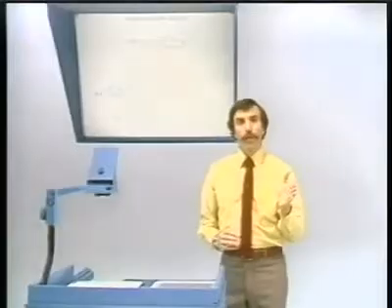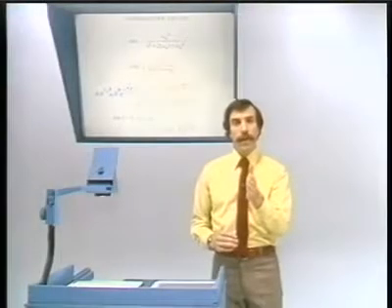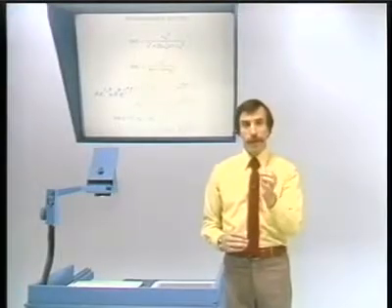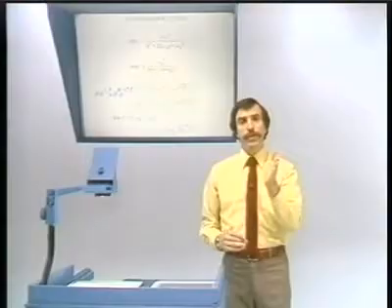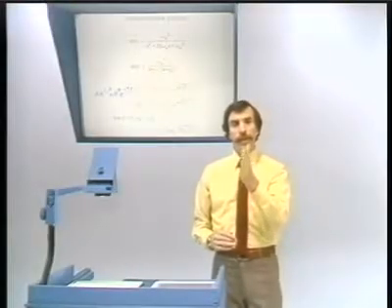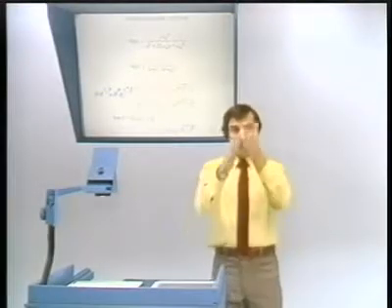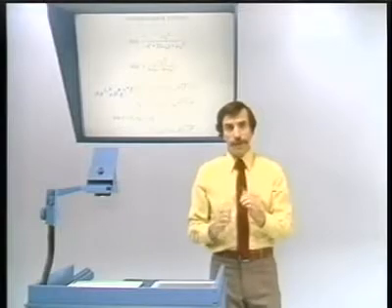And so, in fact, as the poles get closer to the j omega axis, corresponding to zeta getting smaller, in the frequency domain, the resonances get sharper.